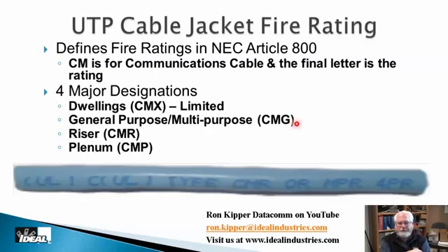General purpose cable, CMG, a lot of your patch cords are utilized for that. General purpose cable is typically designed for horizontal runs, not really meant to go vertically through buildings because the way it burns in a fire, it puts off toxic fume and dense smoke and things we don't really want burning in a fire, but fine for things like patch cords.